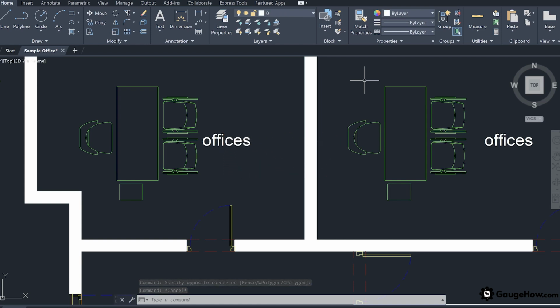Now other than these two options, after AutoCAD 2015, there is another option available which is called lasso. This lasso is nothing but random selection of the objects based on the drawing. Again go to the left hand side of the design and click on the blank area. Now keep the click pressed and move your cursor as per your requirement over different objects.